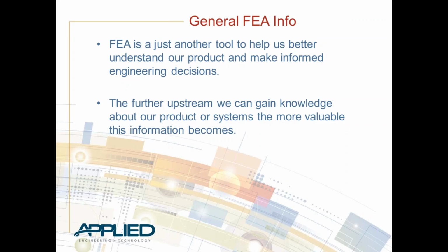Before we had some of these capabilities, you'd come up with a design, you'd maybe calculate out some of the reactions and some of the stresses and the strains by hand. Obviously it's been a while since maybe we had to do that, but it's still good to keep those things in mind. Don't just depend on your computer to do everything for you. So definitely a good idea to still do some of those calculations and free body diagrams by hand, just so you have a good idea of what you're looking to expect.